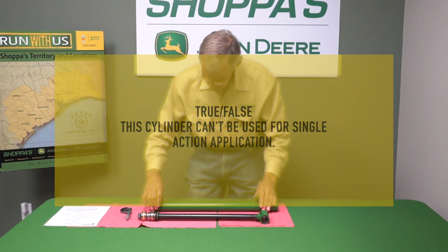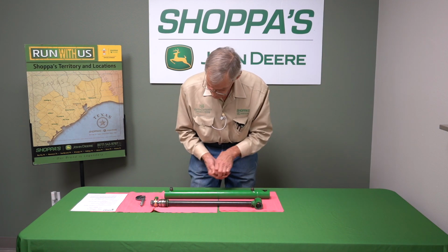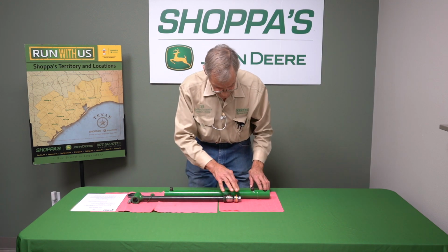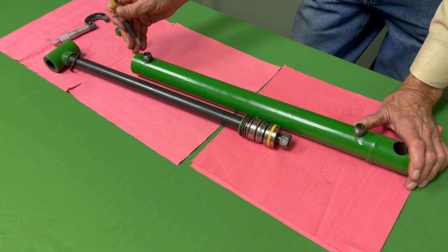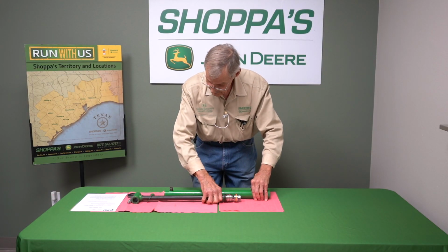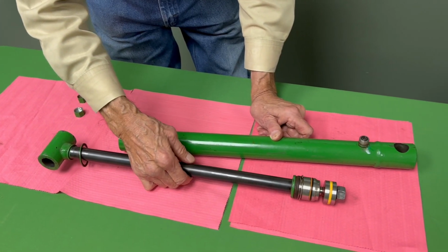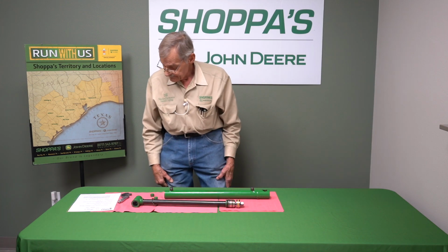These have ports on each end, and you can have this piston rod in here, and piston, and you can have a vent on this end and just apply hydraulic pressure here, and that would move this in this direction, and then having potentially just gravity, once the pressure is relieved here, come back down. So it can be used in single action.